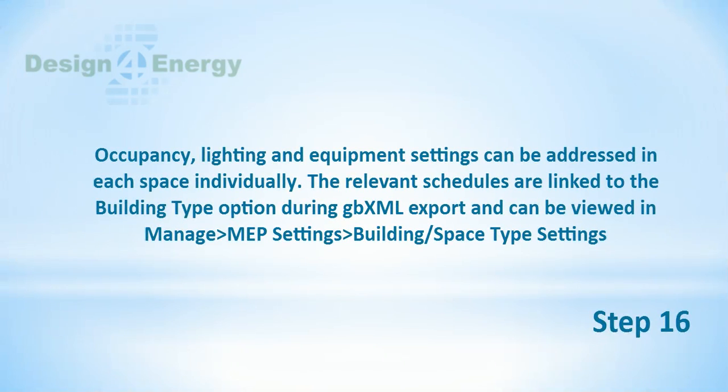Step 16. Occupancy, lighting and equipment settings can be addressed in each space individually. The relevant schedules are linked to the building type option during GBXML export and can be viewed in Manage, MEP Settings, Building Space Type Settings.